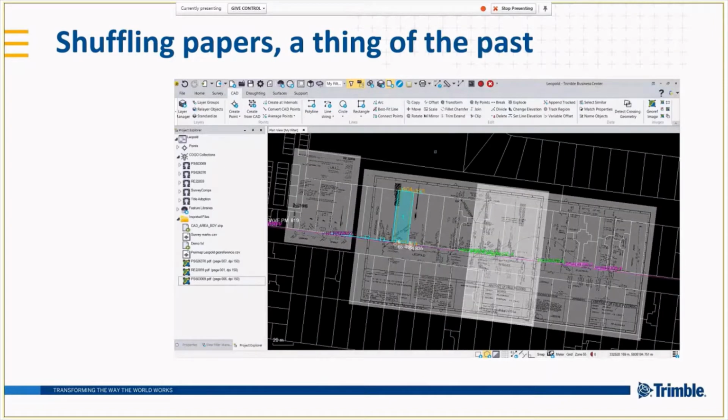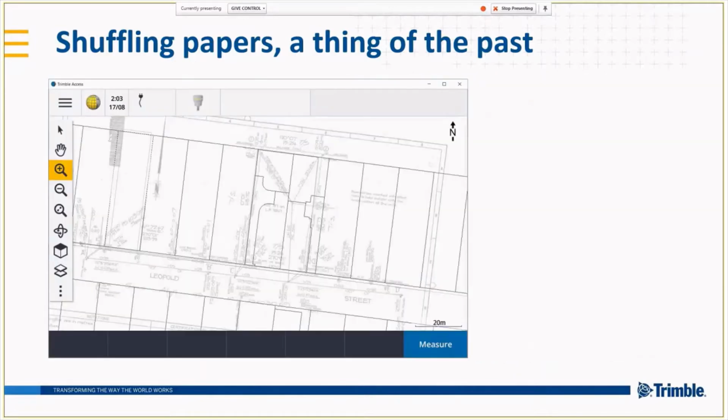Okay, and there it is overlaid, a little bit easier to see where the map base has been overlaid and also the existing surveys. So now when we open up Trimble Access, what we start to see in here is our cadastral map base as a background, and these are applied in this case as an active map, so the line work is selectable, although it's rarely to scale that would be possible for using as a re-establishment.